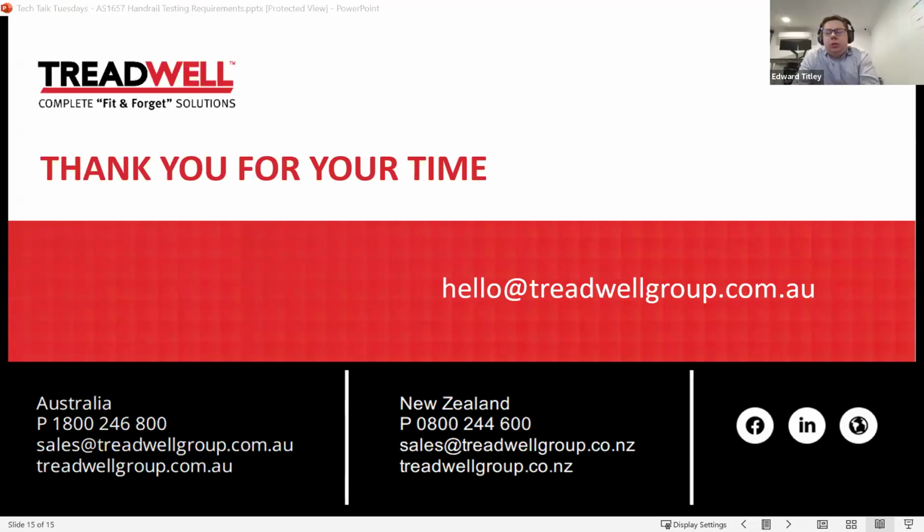Look, that's a good question. Number one is use corrosion resistant fixing. So that might be 316 stainless at a minimum. Could be some more exotic stainless such as 2205, 2507 or something like that. Or the second option, as you bring up very rightfully, is a socket type method where we do a bore penetration in a concrete footing or something like that, and we use grout or a socket.